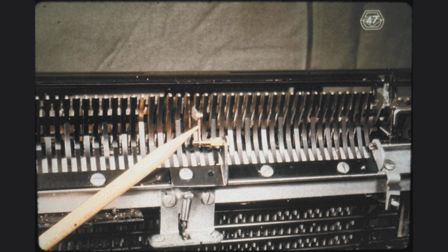In this example, we do not have a spacebar guide clip. Here we only need to free the spacebar shaft so that we can slide it sideways and thus disengage the indicated link from the anchor stud.